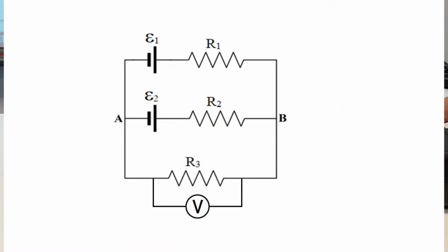Now to measure the voltage, using the voltage sensor is much easier because the voltage sensor, or the voltmeter, is connected in parallel with each element. Let's take a look at the circuit diagram. Notice how in this example we have the voltage sensor connected in parallel with R3 to measure the voltage difference across the resistor R3.